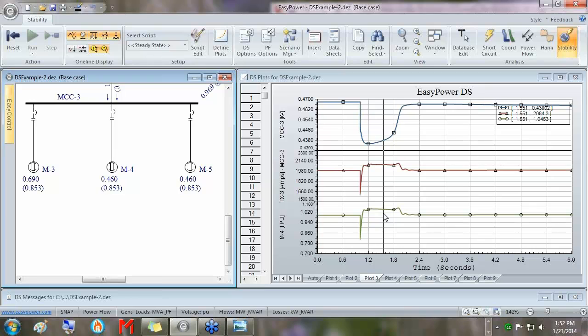Do the best you can on gathering information and data, and put the data in all those other models for all the other motors, so that when you're starting the one, you get the effect of all the others, because your voltage will go lower because of the dynamic effects of those other motors as they draw more current during the voltage depression.